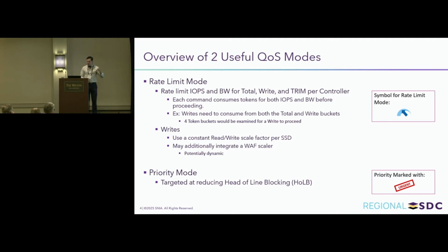But when we look at writes, there's just an example where you have that read to write scale factor, and what happens when you have write amplification. And I think that inside of an SSD brings around some design considerations on how you manage to deliver a good QoS to the host.